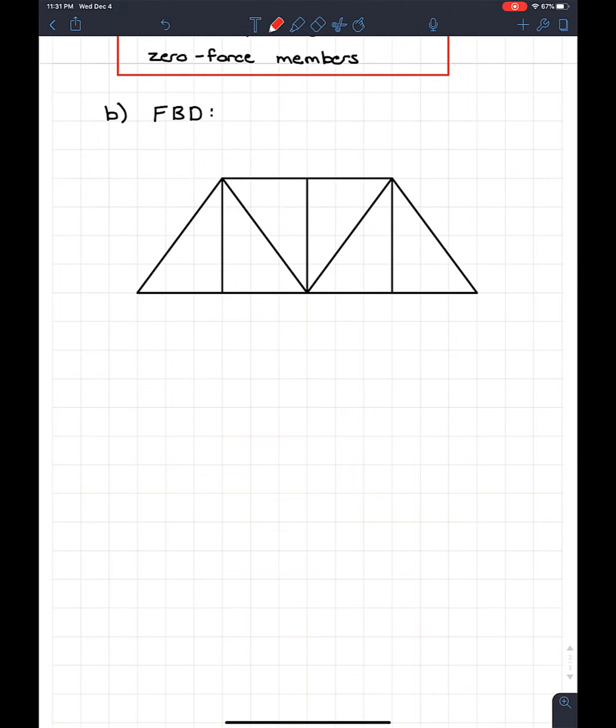So starting with the actual external loads, not the reaction forces, we see that we got a 6 kilonewton load up here, and this one's really sneaky. A lot of students at this point in the course are only used to vertical loads, because besides trusses, we only really deal with loads going up and down. So be careful of horizontal loads. They can come back and bite you. We see that we got 2 vertical loads at these joints here, which are 8 kilonewtons and 10 kilonewtons.